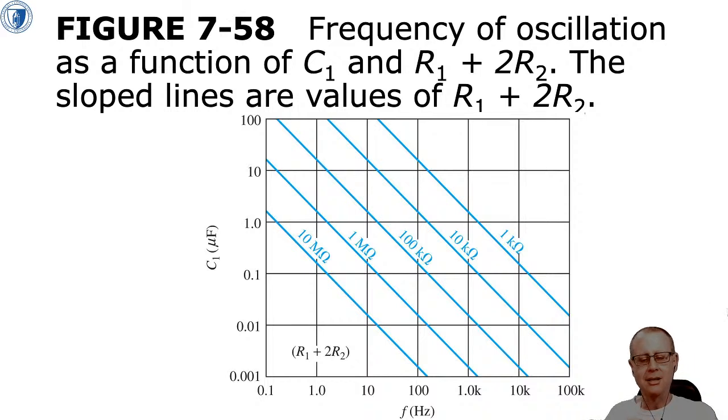Between the first lot of 18, the first batch of 16 and 2 of the new batch, and the second lot of 14, they changed 555 timer manufacturers. I've forgotten who it was. Might have been going from National Semiconductor to, might have been Schlumberger. Anyway, there were two manufacturers who made them. And it turned out that there was a difference, even though they were still 555 devices, between the two manufacturers in this graph.